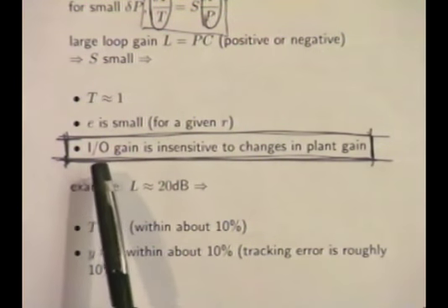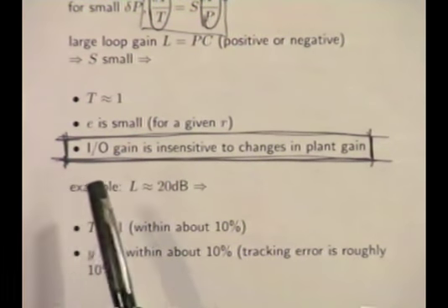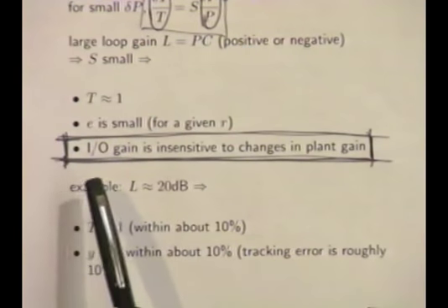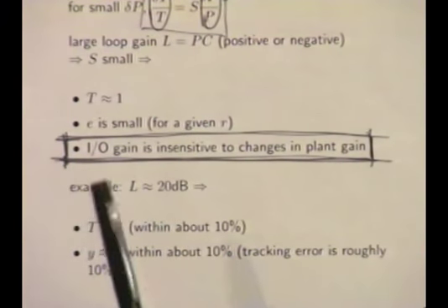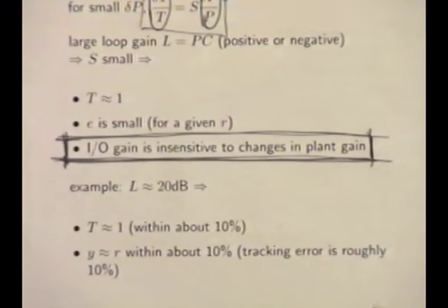Anyway, I can assure you that the actual gain of a little electrohydraulic actuator is going to change greatly over the temperature range. So you need the loop gain there to make sure that when a pilot moves a stick, you're going to get an equal number of degrees of deflection when it's warm and on the ground and at cruising altitude.